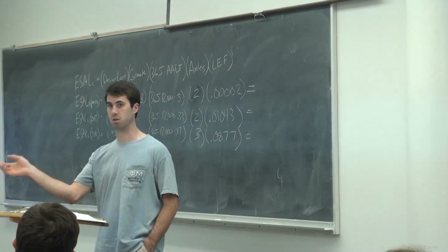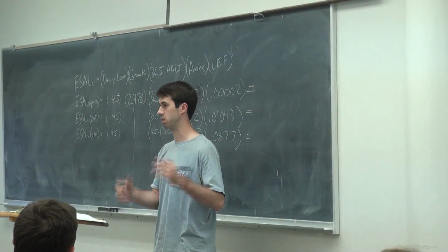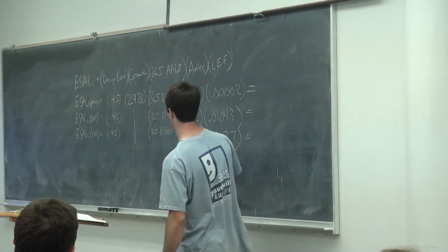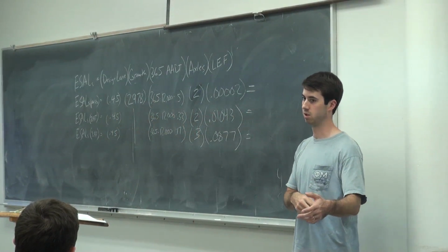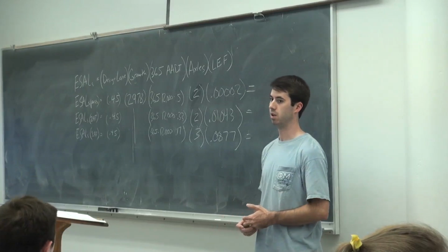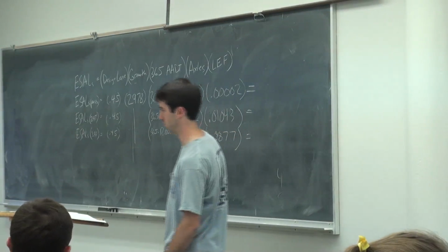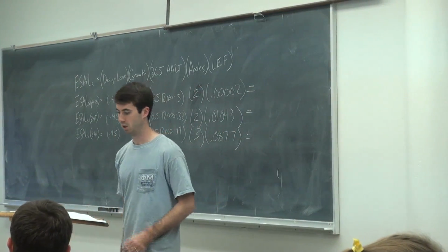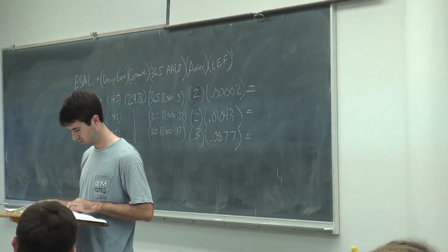Going back to that long AASHTO design guide equation, the log of W18 equals something. Sum this up, and that would be your W18. You put it into that equation to calculate the required structural number, and then you calculate your pavement thicknesses based on that. That's kind of how it comes. Got it? Any questions?